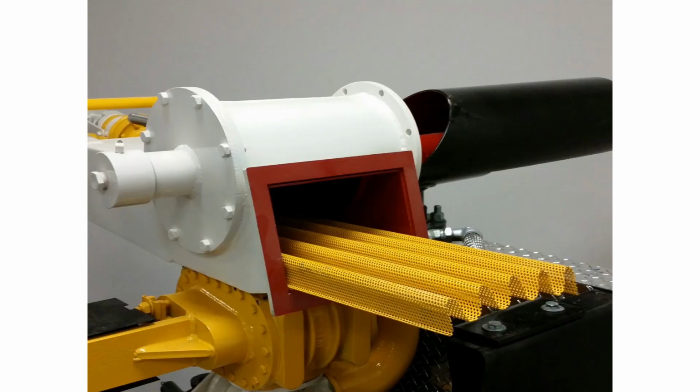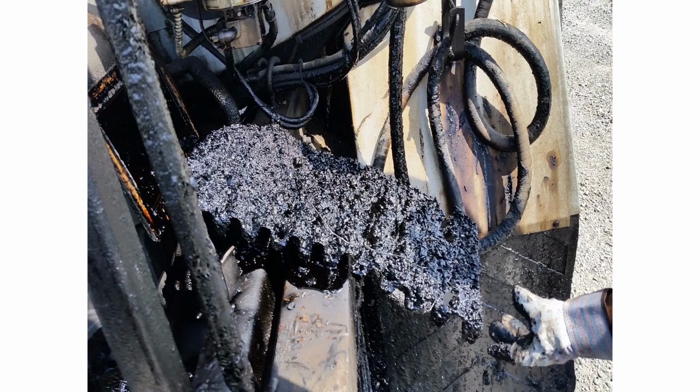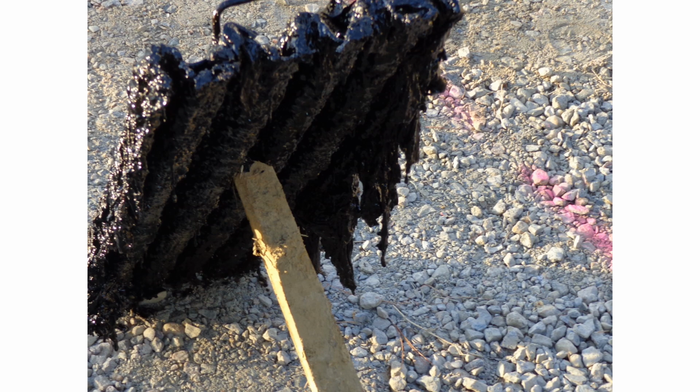Okay? It's got all these holes in it. That oil goes through there and into our pump and then out onto the ground through the spray bar. But if this is all gummed over with a lot of polymers that are in some of our tacks these days, you're not getting the right shot rate because that oil can't get through that strainer. So now what do I do? My strainer's all gooped up. It's all nasty and dirty. How do I clean it?